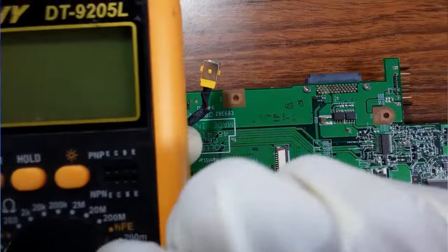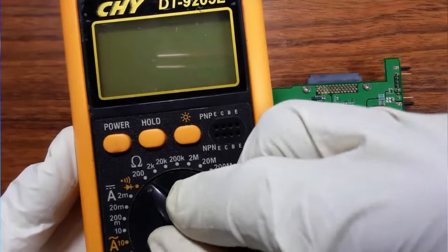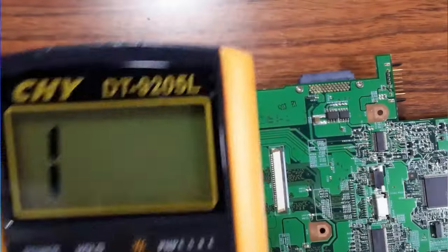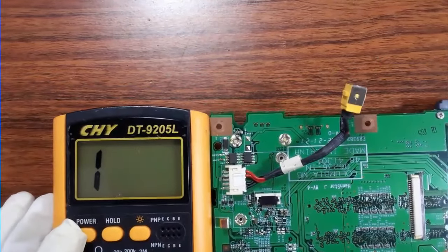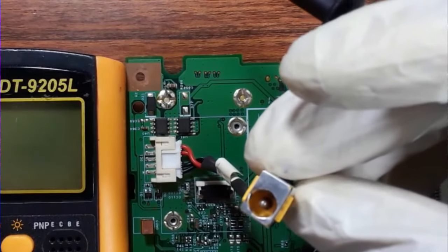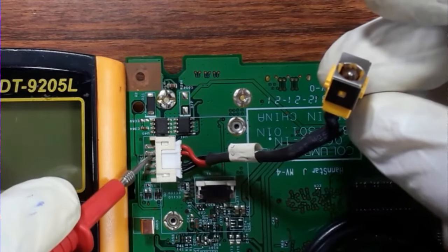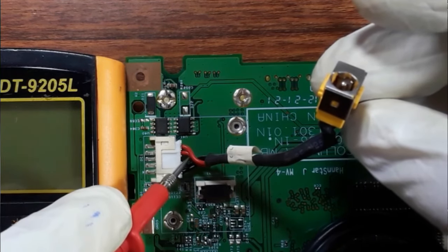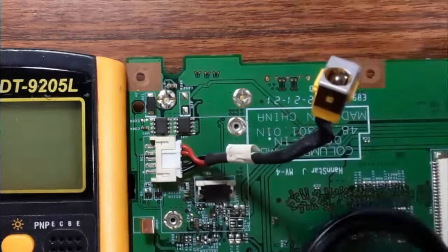So always we should use the multimeter and put the multimeter to the continuity option, as you can see, and then press the power button. Okay, now let's check the continuity. So as I told you before, so we have here the positive terminal goes directly here. Okay, these two pins or two cables are connected directly to this terminal because this is positive terminal.